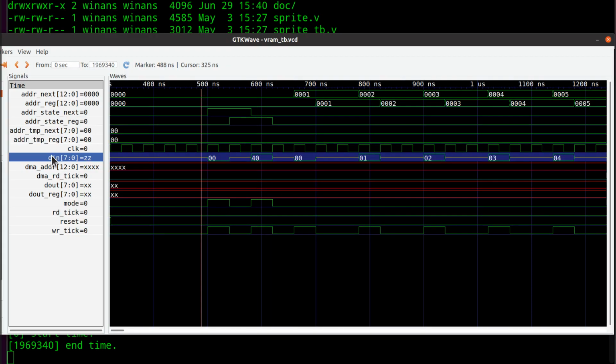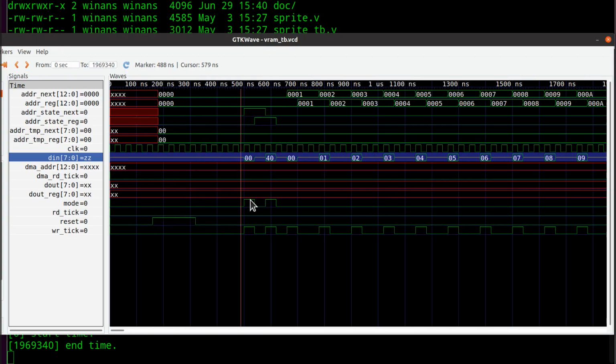Actually, by the time we get D in here, it's gone over the clock domain, and it'll be in a latch. We talked about that before. So this will technically never be floating high Z. It should have been X. I should have put an X in the test bench instead of the Z, but Z also means X with regard to the test bench anyway, so I think we're okay. Maybe an oversight on my part, but it doesn't change the validity of the test case.